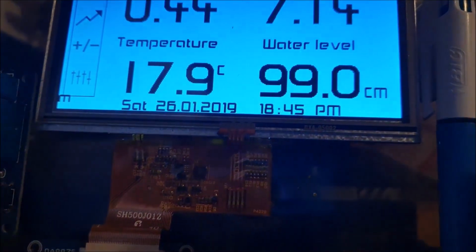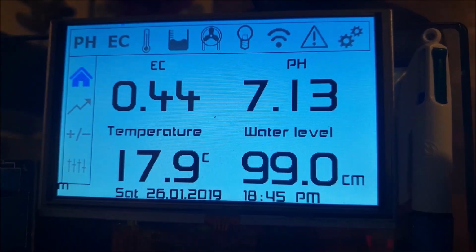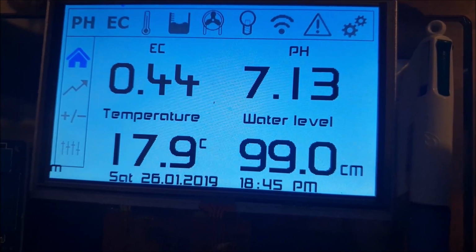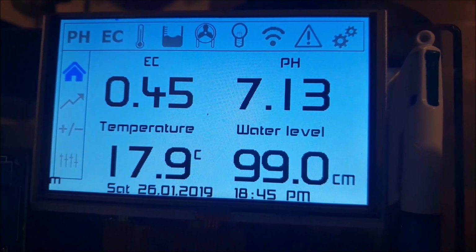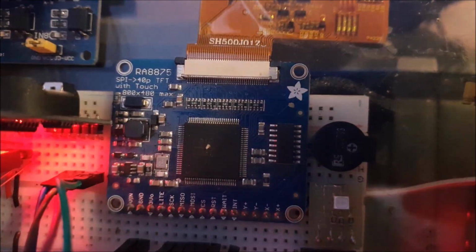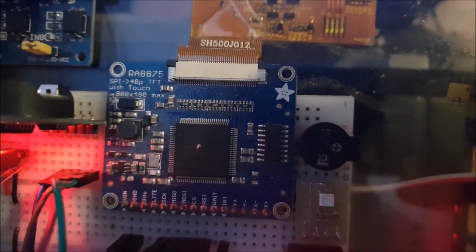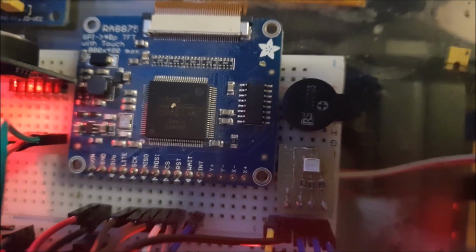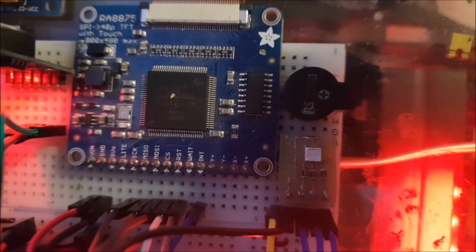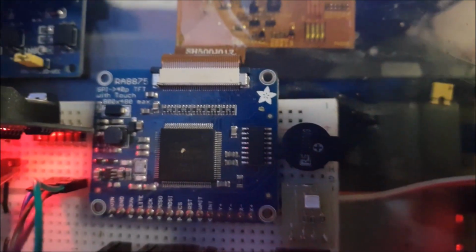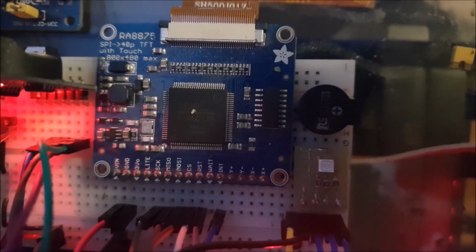Right, let's bash this out. We've got the RA8875 display. You can get these in many versions. I've got the 5-inch version. As I said, I haven't got the digital calibration chip, or touch chip, whatever you want to call it. I'm just using an Adafruit RA8875 touch, it's called a display driver. As I said earlier on, it does have outputs for you to go directly to a display chip, being those Y plus, Y minus, X minus, X plus. That's weird they did in that order, but they did. And essentially it's just got a beefy chip on there to process all that memory.